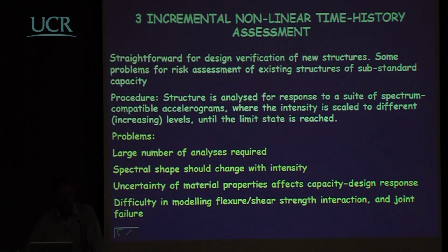Another technique which is popular amongst researchers is incremental nonlinear time history analysis. Basically, the structure is analyzed for response to a suite of spectrum-compatible accelerograms where the intensity is scaled to different increasing levels until the limit state that we're considering is reached. Problems with this? Well, a large number of analyses are required. The spectral shape should change with intensity. In other words, if you're looking at seismic risk, then we shouldn't be just scaling the same records by the same factor.